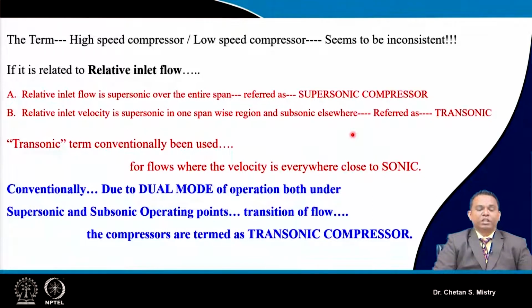Basically, this transonic term is conventionally used when we have flow very near to sonic condition. Now there are different approaches for discussing and understanding the transonic compressor term, but conventionally we have two modes of operation, from subsonic to supersonic or from supersonic to subsonic, depending on the operating points. And we will have a transition of flow happening within the blade passage.